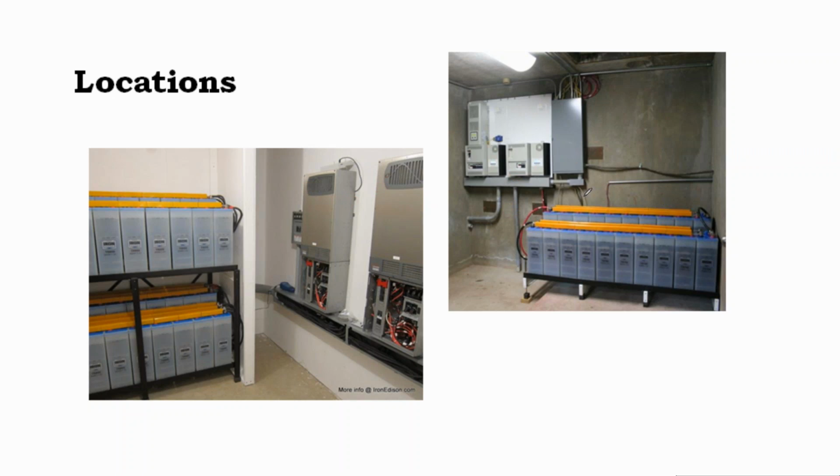You are going to have to take as part of your maintenance, you're going to have to measure the specific gravity of each battery. Now, most of these batteries are going to have multiple cells in them, and so the procedure would be to just measure one cell per battery. But the maintenance procedure would be to come in, unscrew one of these battery caps, stick your hydrometer down it, and do that for every single battery along here.